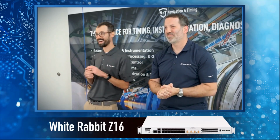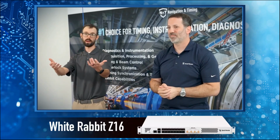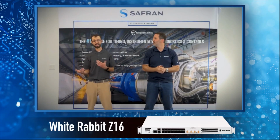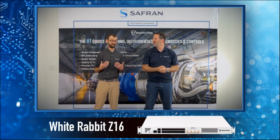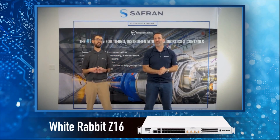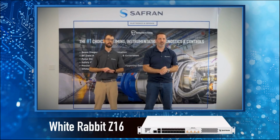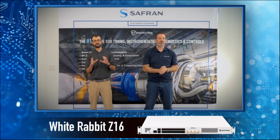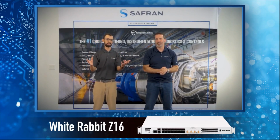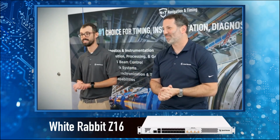From there, it distributes that out over the fiber network to other White Rabbit enabled nodes, using a combination of synchronization and syntonization, words I didn't think I would be using every day, but I do somehow, where we synchronize in time and frequency. So we're sharing the clock, and that's a little bit of how we get that sub-nanosecond accurate timing. The Z16 is very good at distributing lots of PTP or White Rabbit, and because we're very creative with naming, we can distribute 16 of them, which is why we named it the Z16.